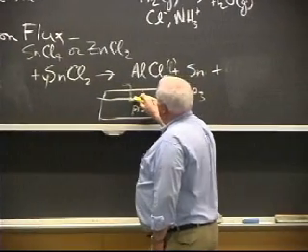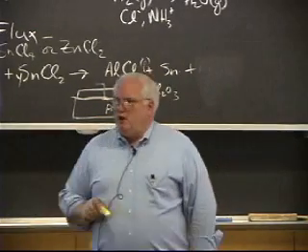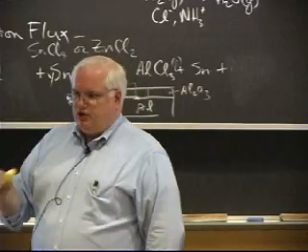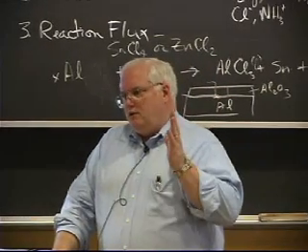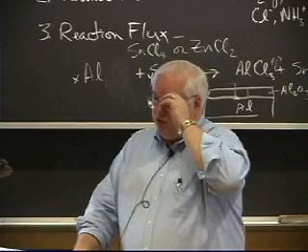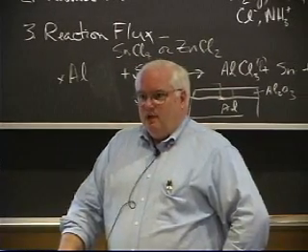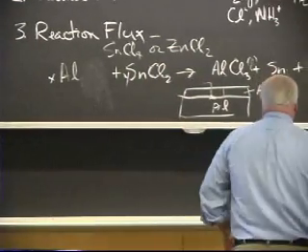So I start bubbling some gas under here, and I start forming a little tin layer, and I pre-tin my aluminum. And if I do it well, and also scrub it ultrasonically or something, I can hopefully float away the aluminum oxide, just like icebergs off a glacier being carried away by the ocean, right? So it's kind of a special thing that's not used very often.